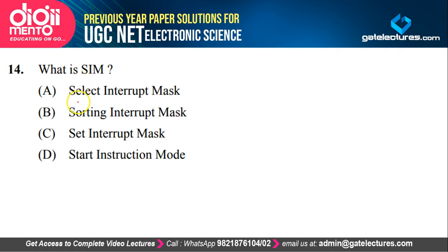So they're asking what is SIM. See, they're not talking about your mobile SIM. This is an instruction in the 8085 microprocessor, which is set interrupt mask. So what is happening basically, 8085 has a number of interrupts. However, you can mask. Mask means delay or stop some interrupts from coming using this instruction of SIM. Another instruction we are having is read interrupt mask, so that you can know the status of those interrupts. Fine. So basically you're giving this instruction SIM.